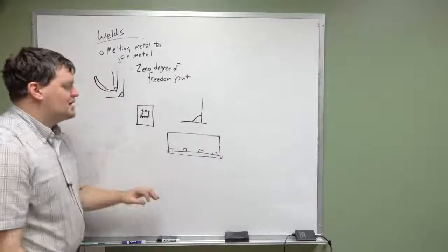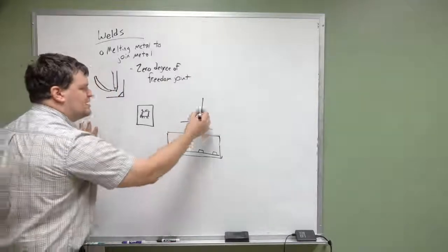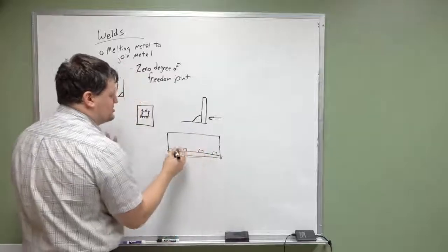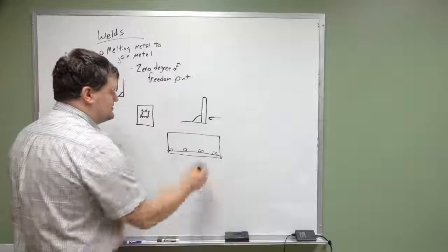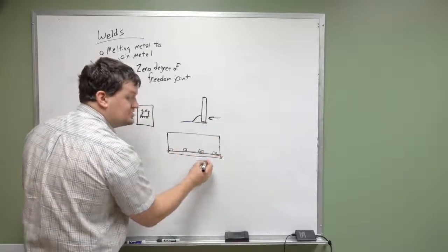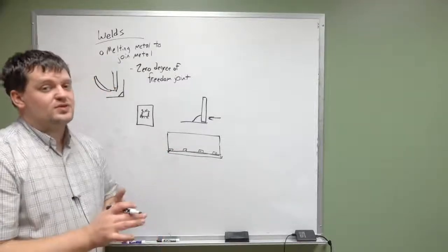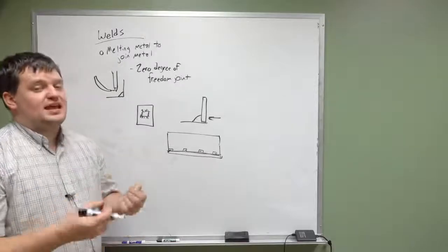So when you have these spot welds, all of the force that's being carried, any forces that are transmitted in this direction, are only being carried through a small area. You don't have force being transmitted down here at the bottom. This is not your location for force transfer. It is through your spot welds. So the important thing when designing welds is that you have to design them such that they can handle the